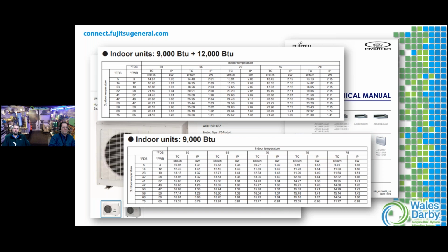But I have charts in this design and technical guide that are going to tell us, based on what you did, this is your multiplier. Now I can take this total load, multiply it by that number, and that's my actual performance I'm going to get. And that's something that I don't see really anybody looking at. And again, when you get to these extremes, we talk about our multi-position air handler. We can run line sets up to 230 feet. Am I going to get the same performance at 50 feet that I'm going to get at 230? No, that's the true answer.